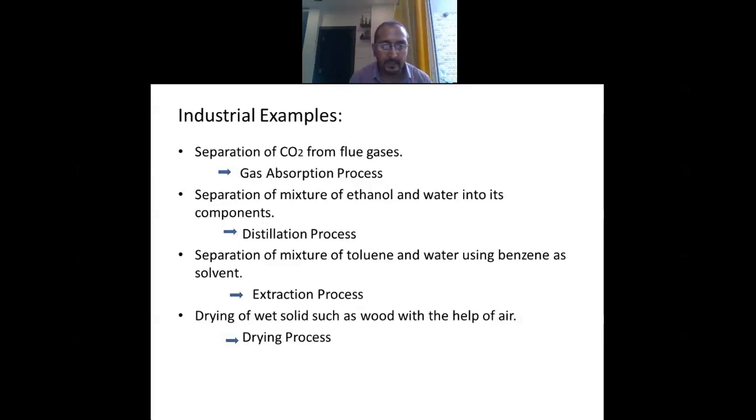The vapor will be richer in the more volatile component, ethanol. If we condense this vapor, we will get another solution with more ethanol and less water. Suppose that composition has 70% ethanol and 30% water. In that way we have separated ethanol and water into its components by the distillation process.